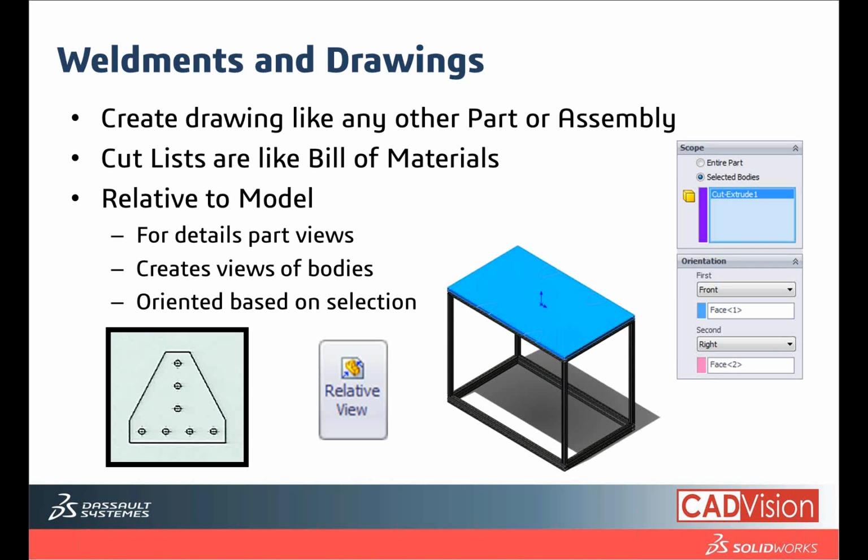Once you have updated your cut list, it will group all the same size multi-body parts together. Then right click to properties and check what you have inside. Customize your properties, customize your parts properties, customize your multi-body properties. In other words, customize your cut list. So we have prepared all of these, and we are done.